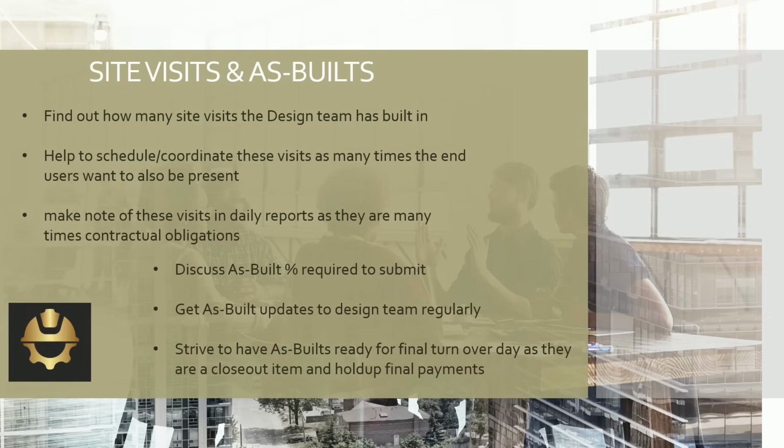So if you're working for a small company, and we both have QC'd for smaller companies, it could mean once a month you take your as-built package to your printer, having them scan it electronically so you can get a disc to the design team so they can see all the physical red lines that are made in your site trailer. It could mean you're set up with a plotter type scanner, and you can feed them through and scan them yourself.